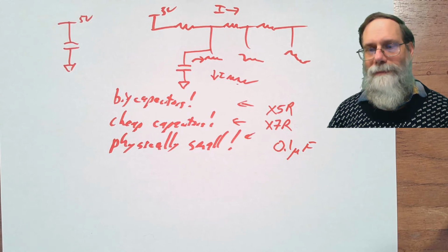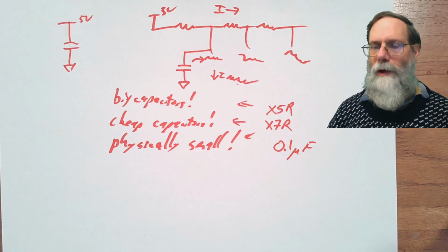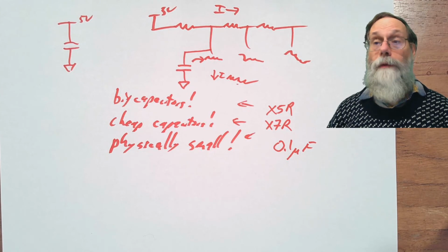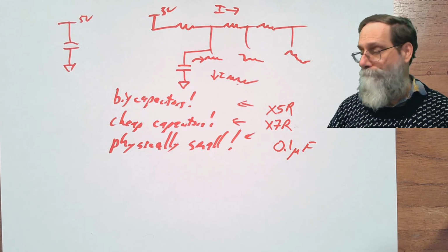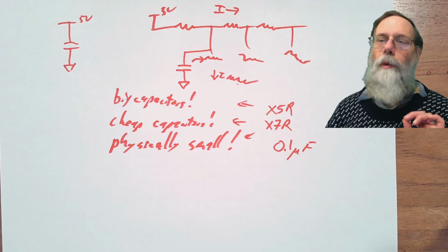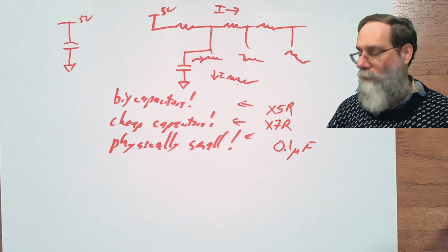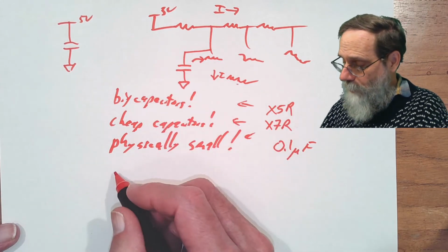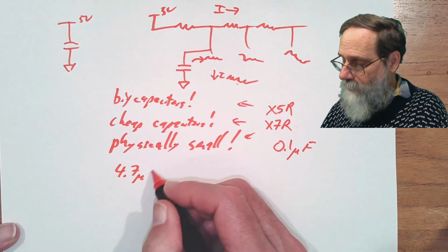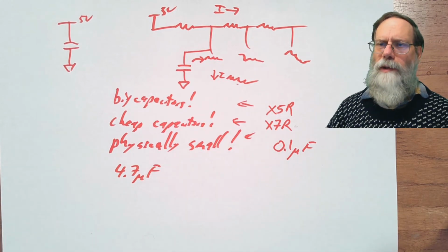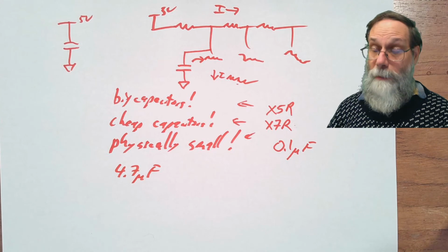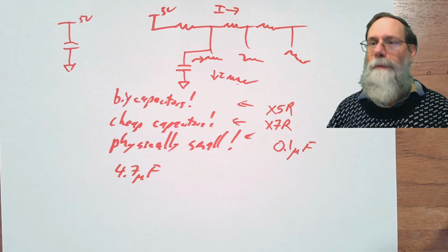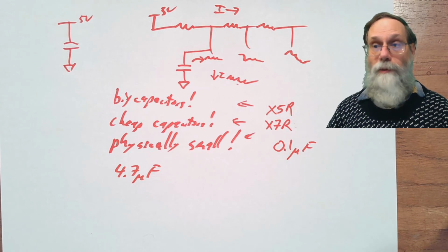And you don't gain a lot by going just a little bit bigger. These are good enough for most digital work where you're working with very high frequencies, but they're the ones you put right next to the chips. I've been using for my own work usually more like a 4.7 microfarad capacitor. That's because I'm usually not working with the tiny little chip capacitors that are surface mount components, but the little bit bigger disk capacitors like we use in class with the breadboards.